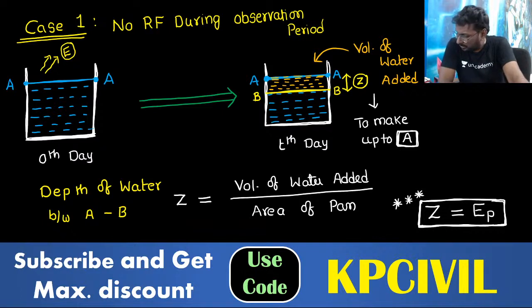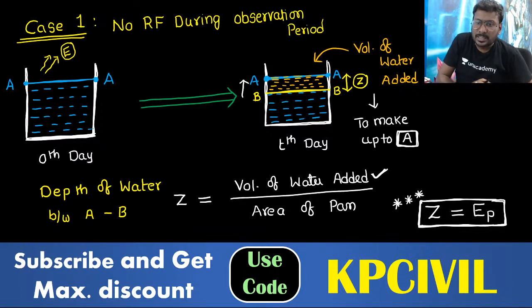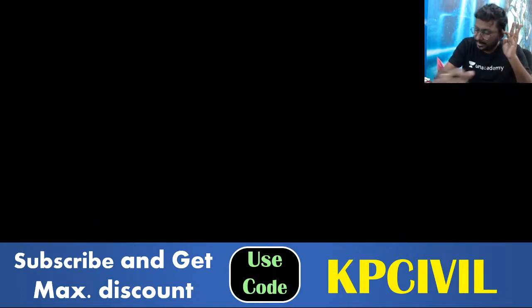So do you understand now, Avijit Chakravarti? Do you understand how volume of water is taken using a measuring jar? Take a 5 liter measuring jar, fill the water. All 5 liters over, again take one more 5 liters and fill it slowly. So you understand, total to raise water level from B to A, how many liters required, that number of liters you take as volume of water added, divided by area of the pan, Z. Then Z is equal to EP because no rainfall. No need to add anything or remove anything. Now this is over. We'll go ahead.